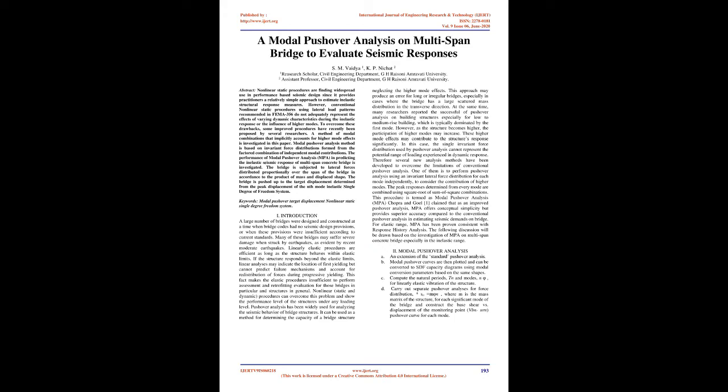However, conventional nonlinear static procedures using lateral load patterns recommended in FEMA 356 do not adequately represent the effects of varying dynamic characteristics during the inelastic response or the influence of higher modes. To overcome these drawbacks, some improved procedures have recently been proposed by several researchers. A method of modal combinations that implicitly accounts for higher mode effects is investigated in this paper.